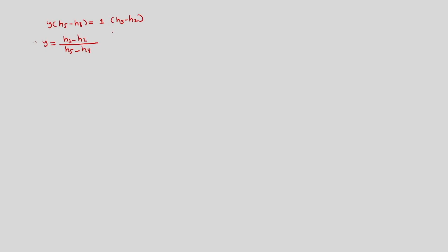So it turns out to be Y equal to 695.35, the numerator based delta H, and the denominator based delta H is 2068.6. So we will get Y as 0.338. This is the mass fraction which is extracted for the process of drain cascade backward.